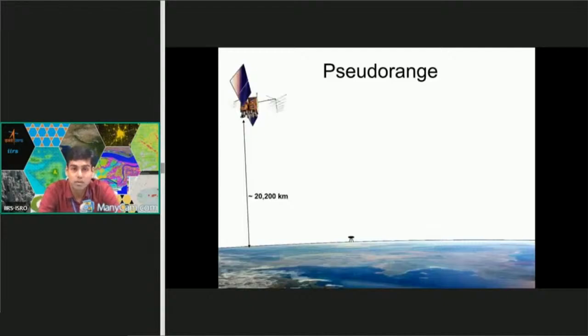The pseudo range. What is pseudo range? Pseudo range is when our GNSS satellite transmits electromagnetic waves in the microwave range. Basically it is L1, L2, L5. It comes in this range and carries different types of signal. It carries code signal and carrier phase. Basically, this is the distance we use when determining the latitude, longitude, and height based on distance calculation. So it is called pseudo range.